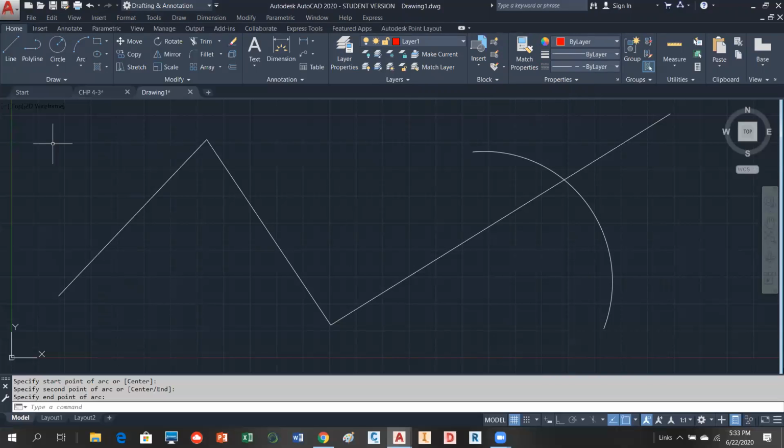So let's go and draw a polyline, and you should notice now as you draw on the screen, you're getting a red polyline that has a centerline line type. A circle will take on that same. So anything that you're going to draw here is pretty much going to take that on. If I do a rectangle, it'll take on that information as well. Is that working? Yes. Not sure what that is, but anybody have problems?